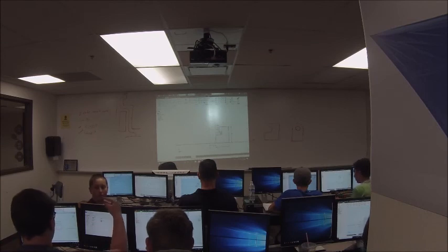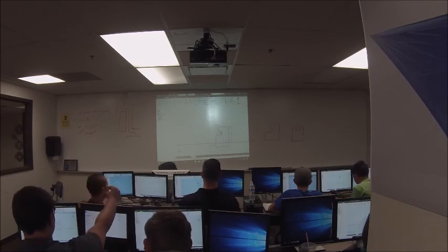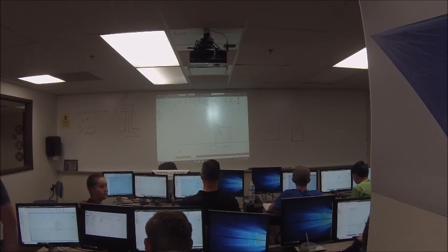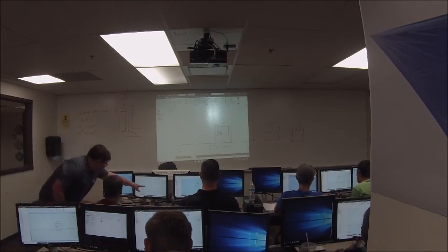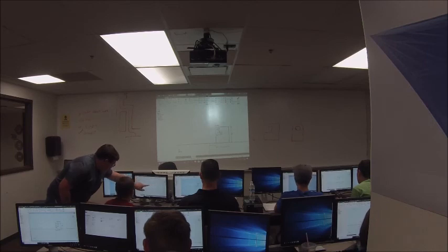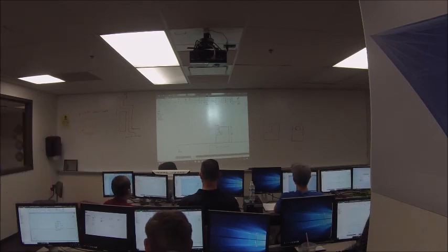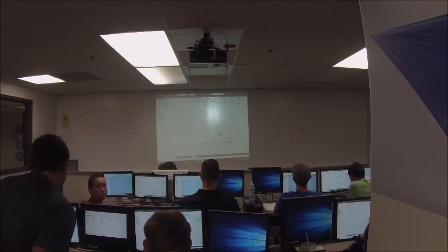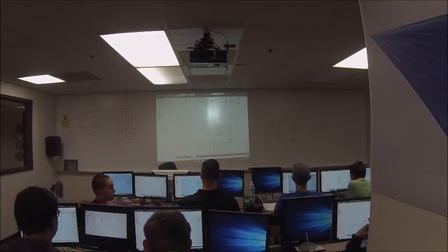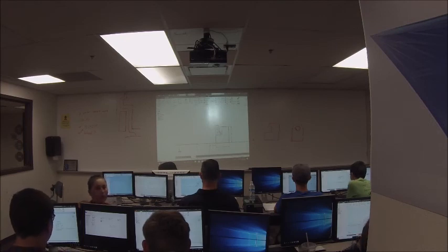If you look at your sketch, if you did this, and this, well then this is a driven dimension because it already knows this. So basically, I only have 2 more left. If the program already knows what it has to be, then it'll make it.